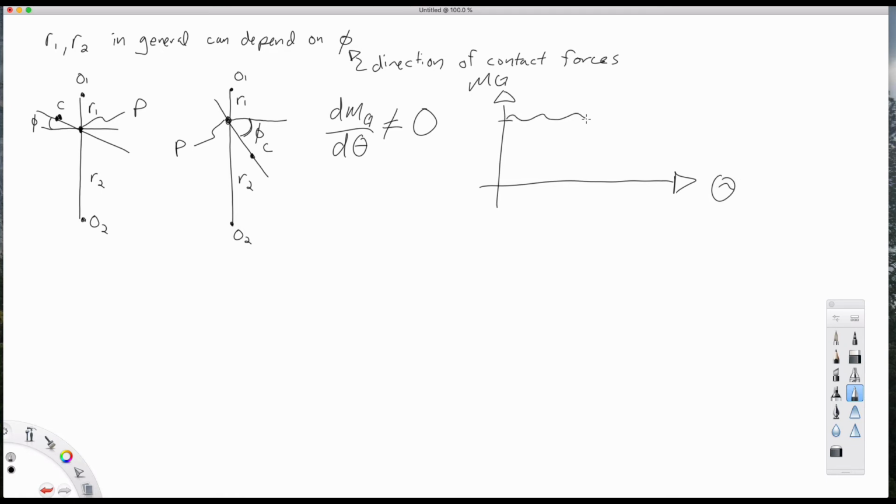And if that's the case, we're going to have a value for the speed ratio that varies with position, and this can cause all sorts of mechanical problems, including torque ripples, additional fatigue problems, vibration problems, and so on. We need to design a gear set that has a constant speed ratio. So now with all of this information that we've gathered, let's take a step back and reason through the requirements that are in place to make sure this happens.